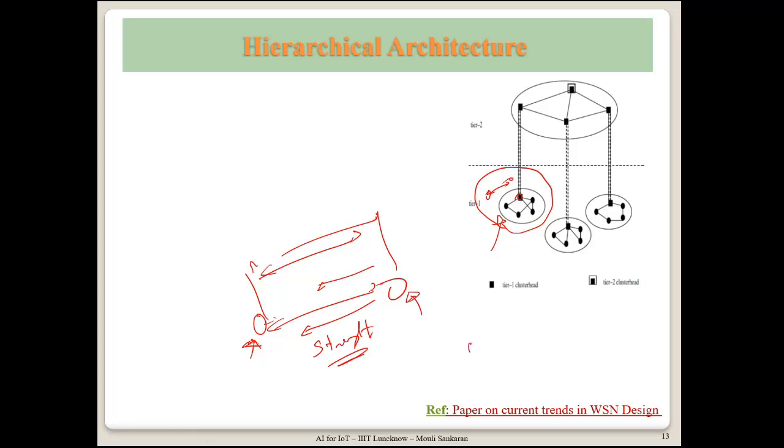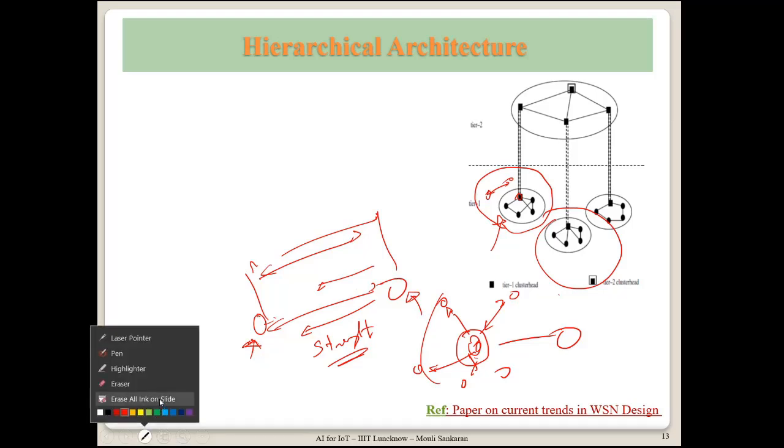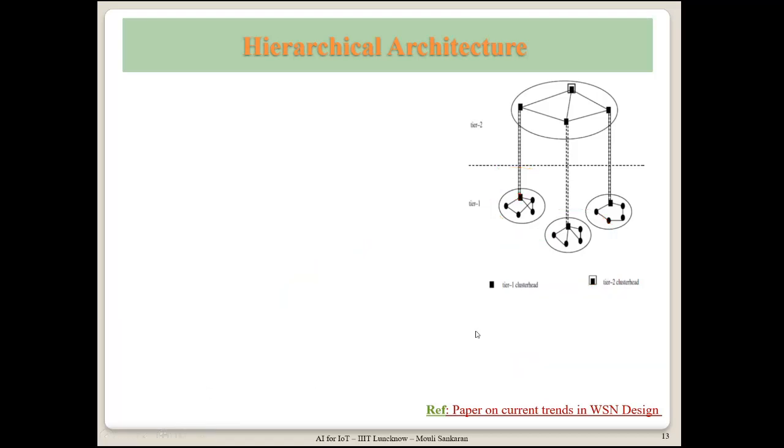So they don't radiate more power than what is needed. If all the devices are nearby, they don't transmit more. That means they avoid disturbing the other clusters with what is transmitted by this sensor node, so we avoid interference between the clusters. At the same time, we save power in each of the nodes, and we also do the communication in an efficient way because of these minor optimizations in transmitting power on each node. These are RF techniques used to save power on devices, and this is done in our mobiles and Bluetooth devices also.